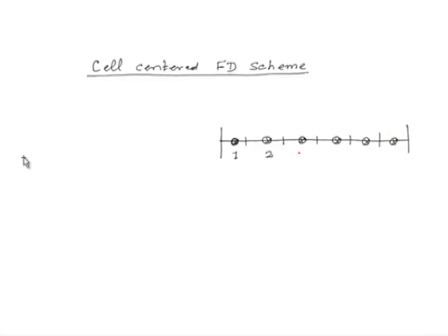Node 1, 2, 3 and so on, n minus 1, node n. This is our right boundary where we have our convective boundary condition specified, and we had as left boundary T = T bar. Here we have -k ∂T/∂x = h into (T - Ta).